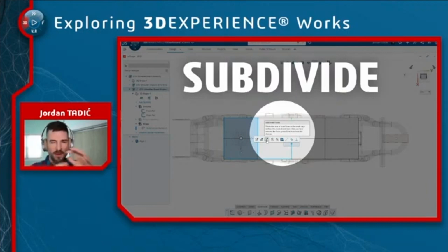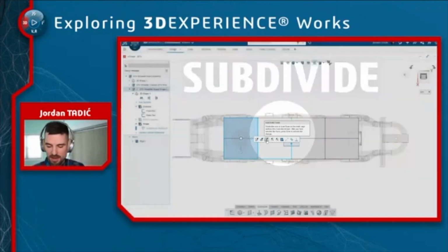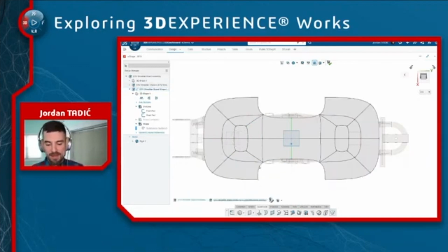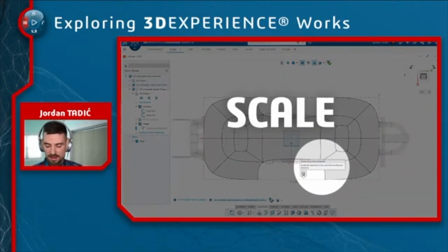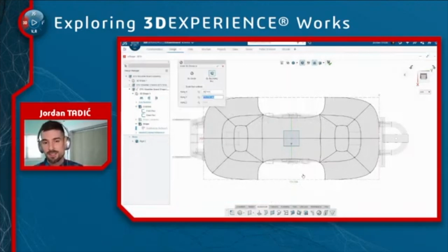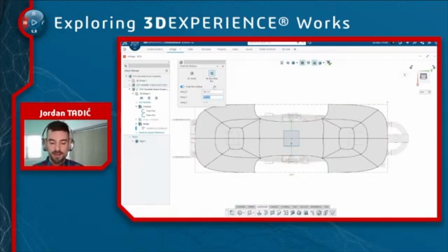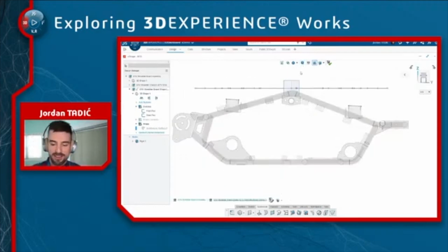This is a great way to add more control points in a localized area. So if I want a little more detail in this area, then I subdivide the faces. I get that many more vertices that I could push and pull around. And I can extend surfaces. I can turn on the bounding box to make sure that this is scaled to the exact dimensions that we need them to be, just like I did before. That's pretty much a part of every single one of my modeling workflows anymore, because size is important.